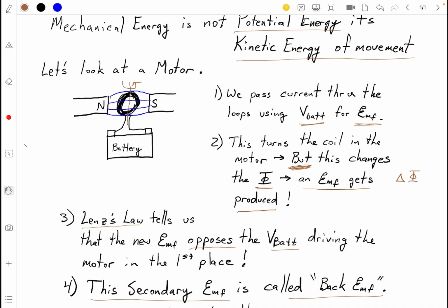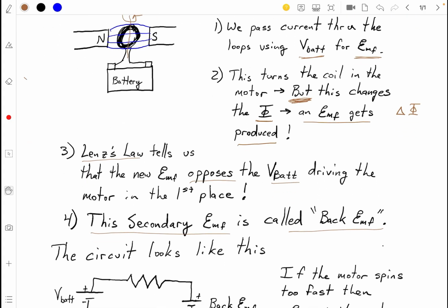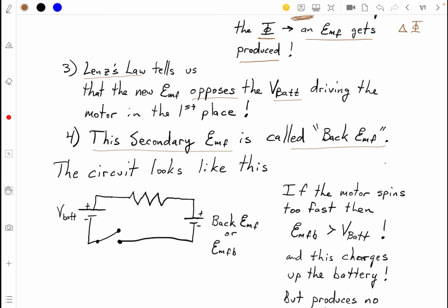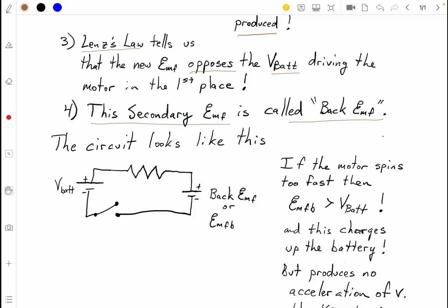But since we're using it as a motor, it gives us this back EMF. So back EMF completely comes from motors only. Think about how a generator is not going to generate a back EMF because you're taking the mechanical energy and shoving it straight into a battery. But this way we're taking current, we're producing this thing, and it's giving us a back EMF, right?